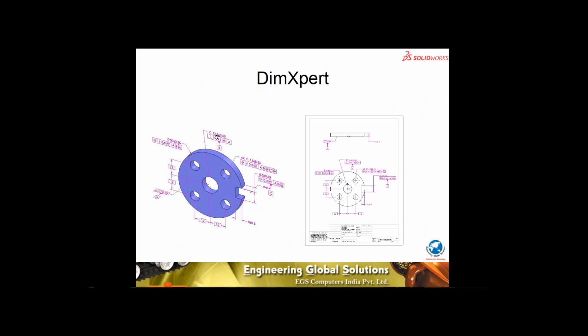Now, you can see a part definition released using the three-dimensional annotations with DimXpert, which are live annotations representative on the features themselves. And you can see the basic dimensioning, the feature control frame, and the associativity of the different levels of control, starting with the size tolerance, the form tolerance, the orientation tolerance, and the location tolerances being provided, and automatically representing the same in a two-dimensional drawing, laying it out in a clear manner and sending it out.